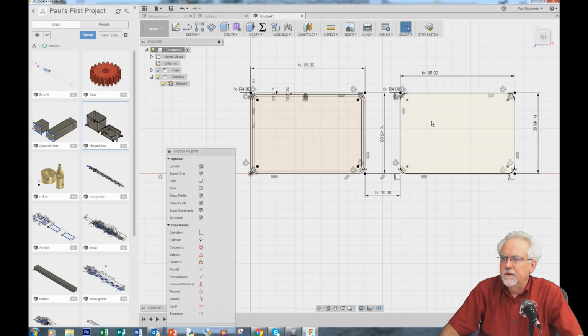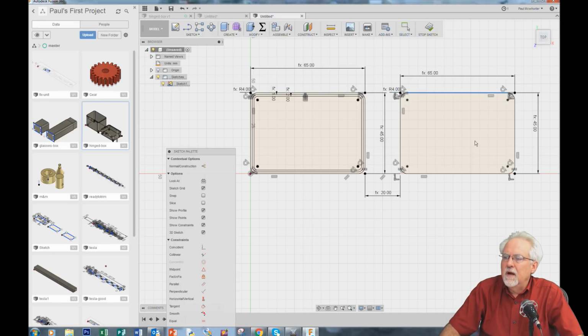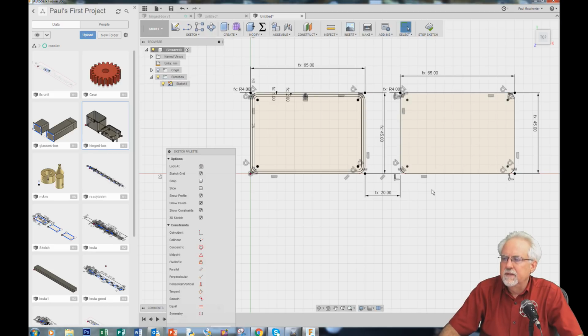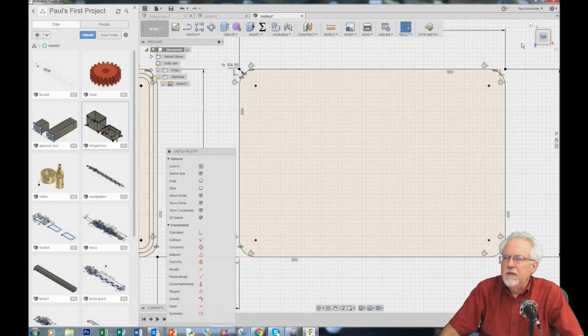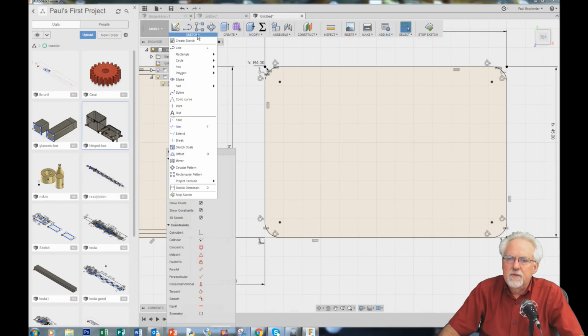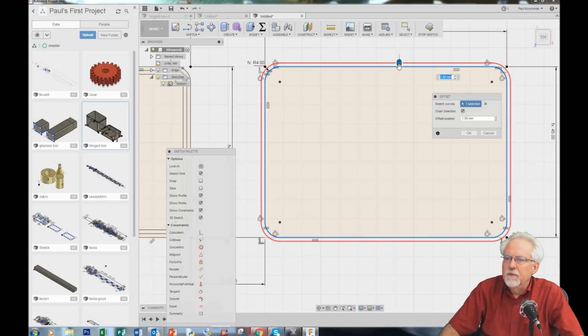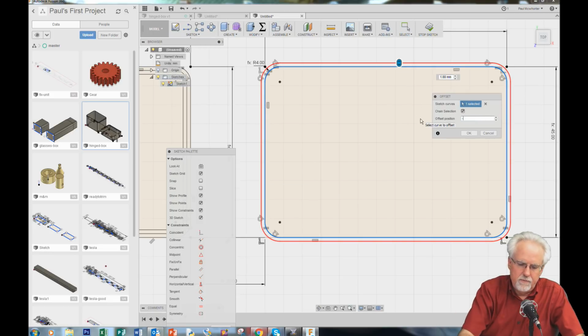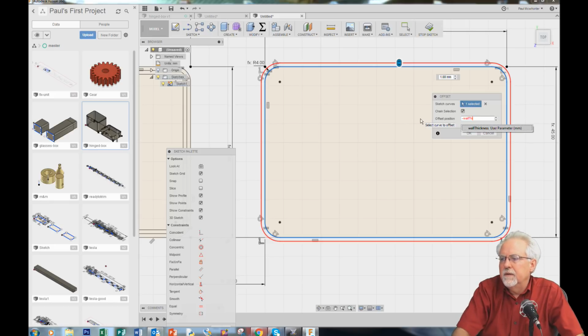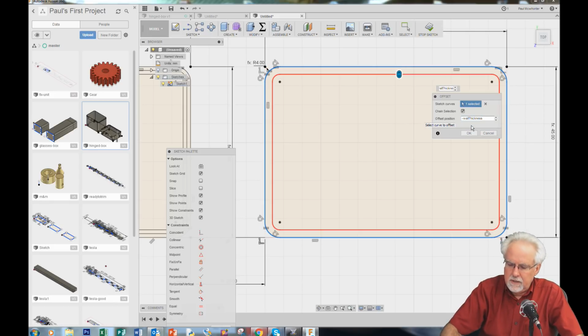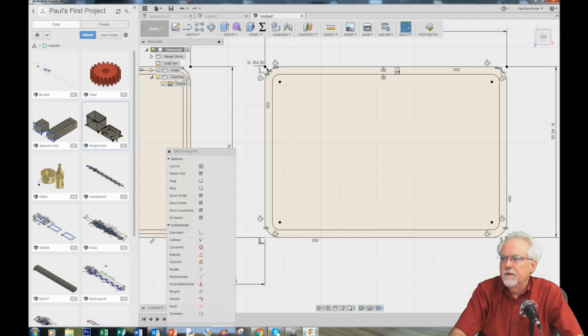And it fixed it there. All right. Now let's make sure we're still locked down to that corner. Yeah, you see how everything is black, and so that still looks good. We now need to do our offsets with the associated annoyance of having to fix them. So we're going to say offset from here, how much? Minus wall thickness. Got it. Enter. All right, and now what do we got to do? We got to go in and fix it, and we got to say wall thickness.